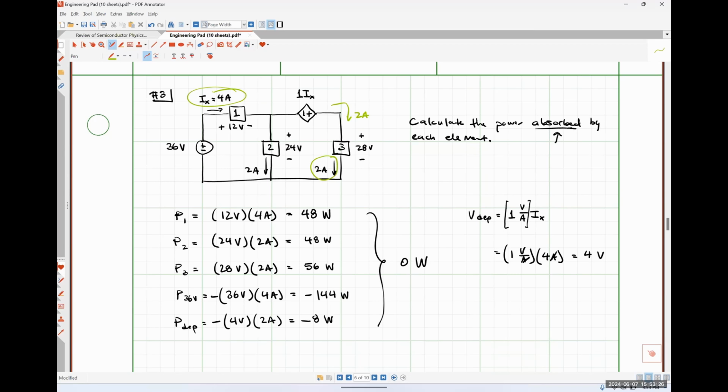That 4 amps that comes out of element 1 gets evenly split between any elements on the other side of element 1. So you're effectively asking about Kirchhoff's current law, and you are correct that if 4 amps is flowing into this node, then 4 amps has to flow out of that node as well. And we'll talk about that in much greater detail on Monday. Okay. I remembered that from 120, I believe. Yep.